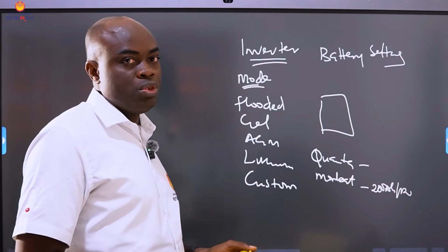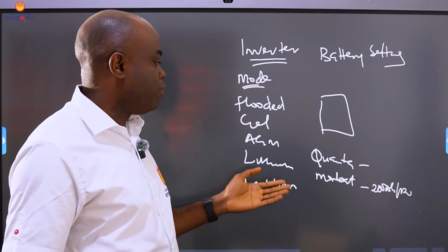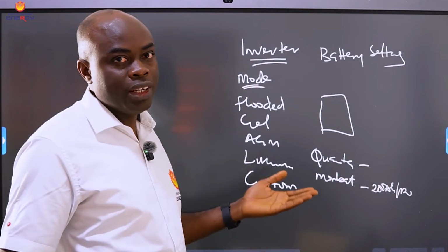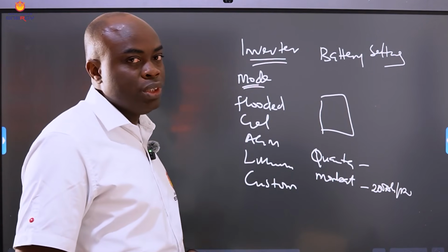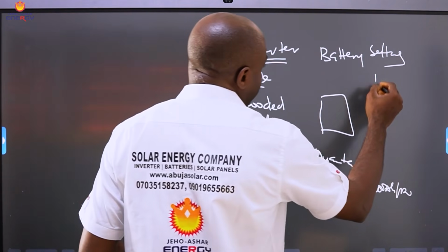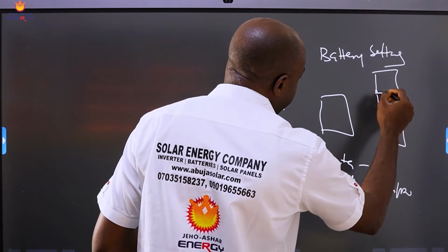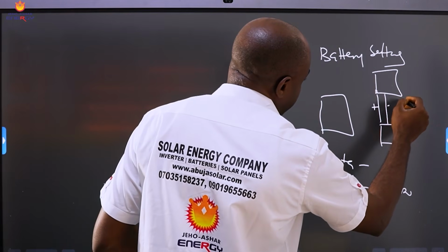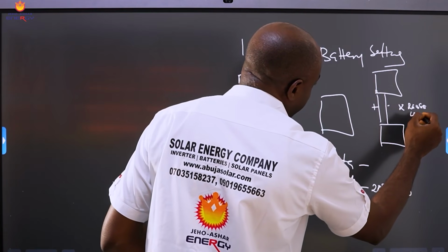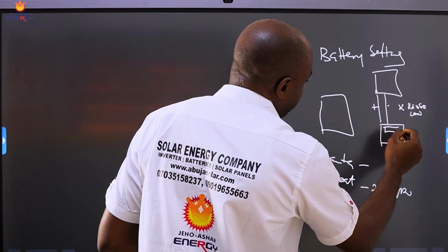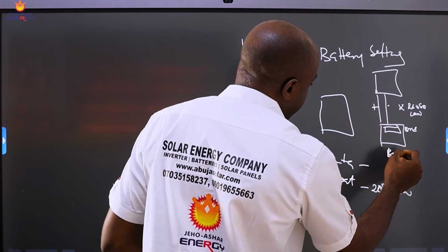And what that custom does is you set the charging voltage, the low cutoff disconnect voltage, the floats, the charging currents, and other information. So once you pick that, what you are doing is this. You only have an inverter machine with a lithium ion battery with only the power cables, positive and negative. You don't have your RS485 or CAN communication. And this battery has a BMS.